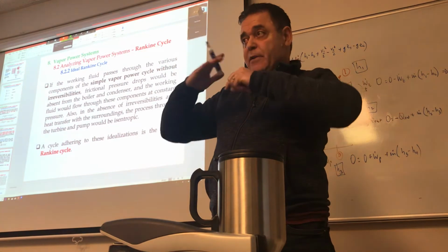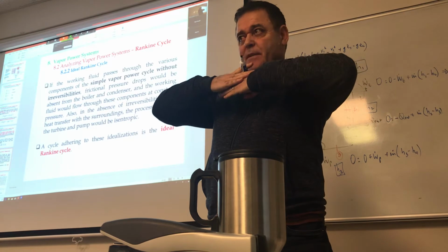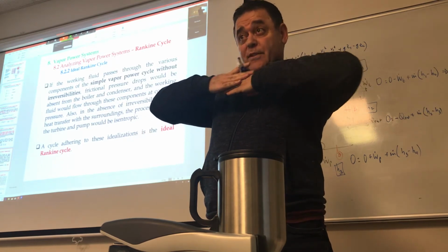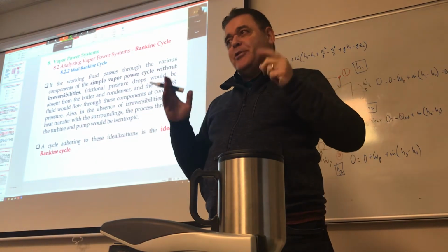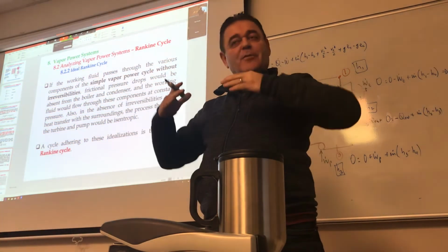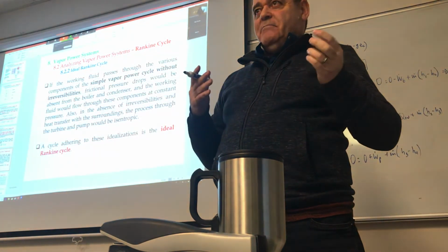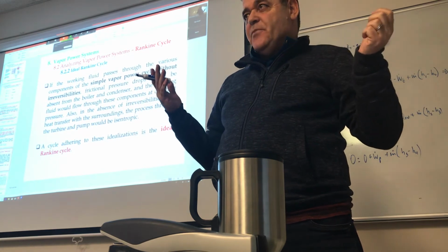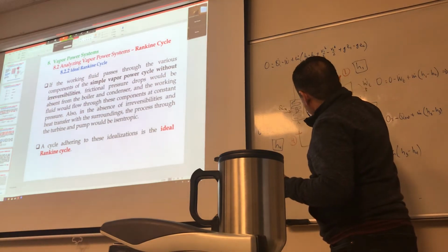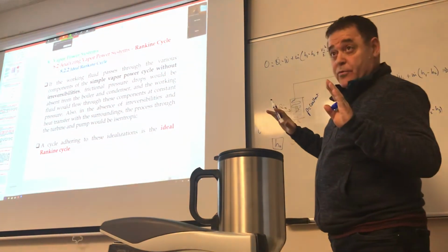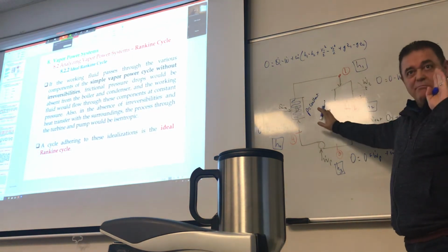because the flow is always subjected to some friction, because the fluid that is against any solid surface is being stopped. And because the fluid is a Newtonian fluid, there is a shear stress that is created against it. Now, if we assume that there is no friction, the fluid, as it flows through the boundaries, just slides across the boundaries. So, does that create any pressure losses? No. So, we will assume that here, P is constant. It's obviously not true, but ideally, I should say, we can call it that.